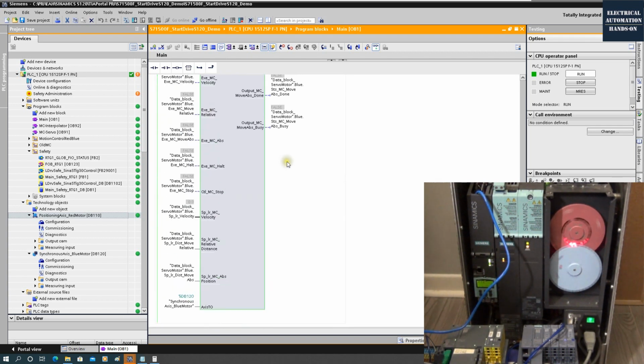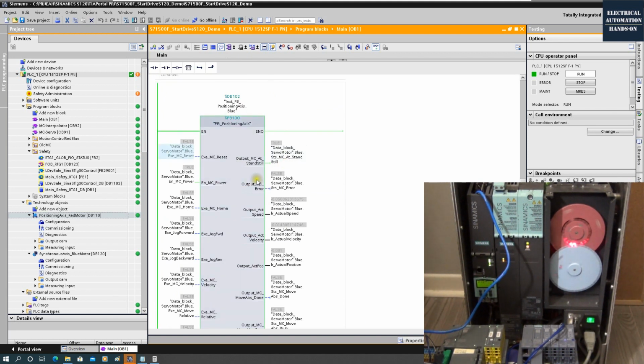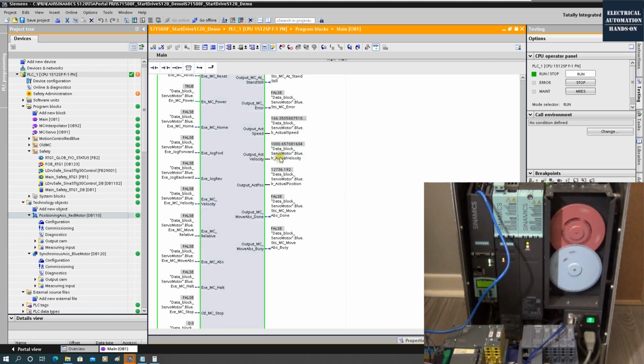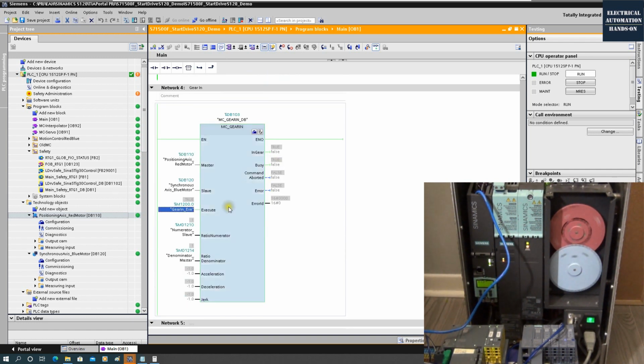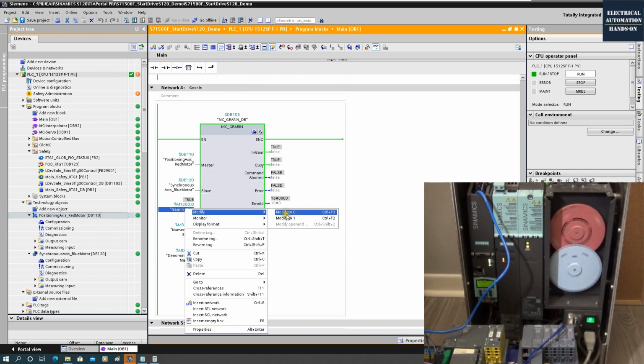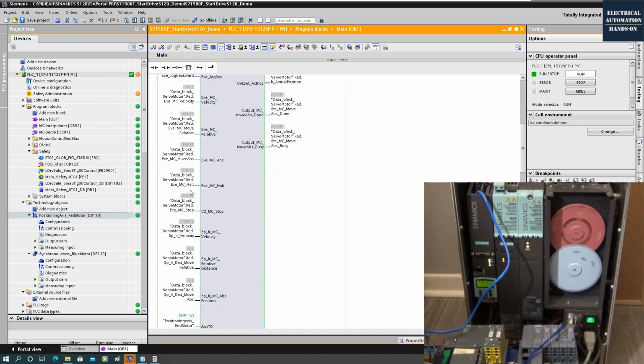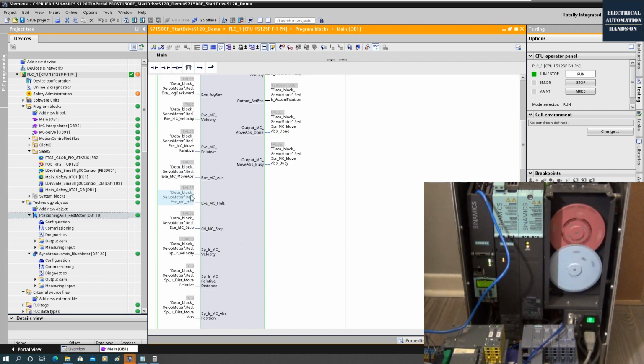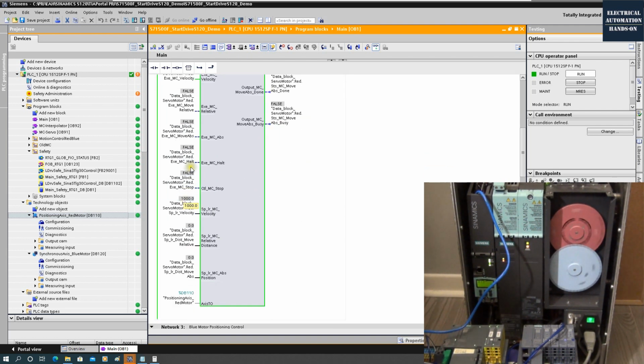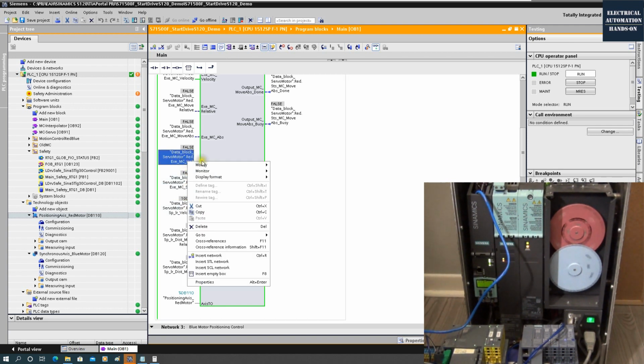And then let's go back. For this blue motor, we can see its actual velocity is running 1000. Okay? And this execute command here is a rising edge command. So if I turn it off, actually it doesn't matter. Okay? And now even if I turn off the execute command, the gear relationship is still running.